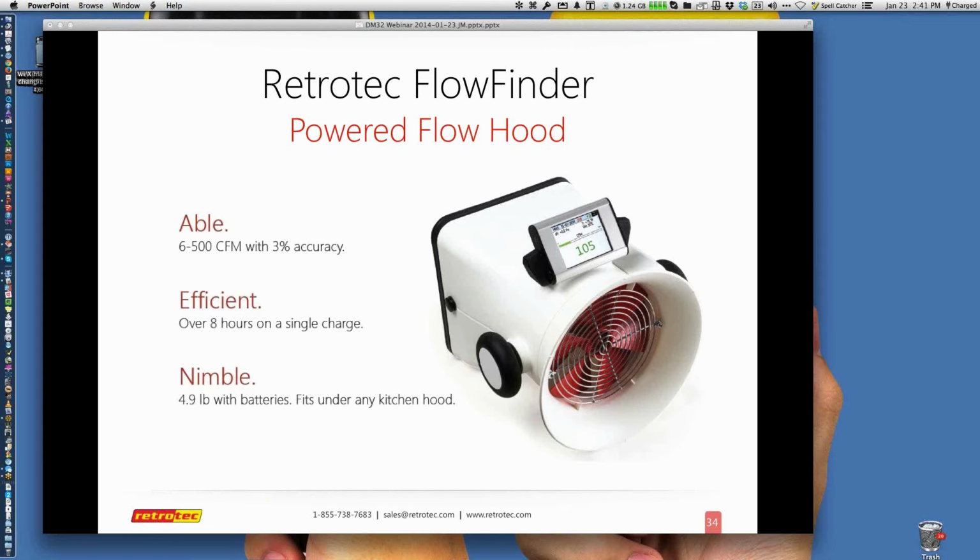So it keeps creating flow until the pressure at the register is zero. And this particular device has a capability of pressure near zero down to 1/100th of a Pascal. Even with the best of our gauges, we have trouble getting 0.1, 0.2 on a good day. So this one is at least 10 times better at measuring zero flow than anything else that we've ever come across. So it's an amazing piece of equipment.